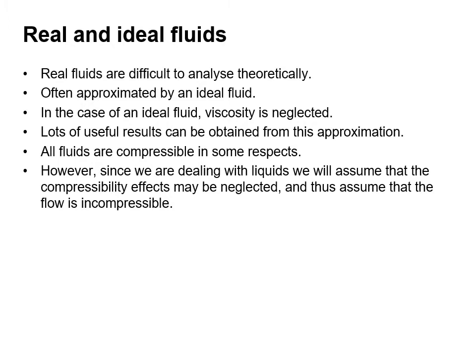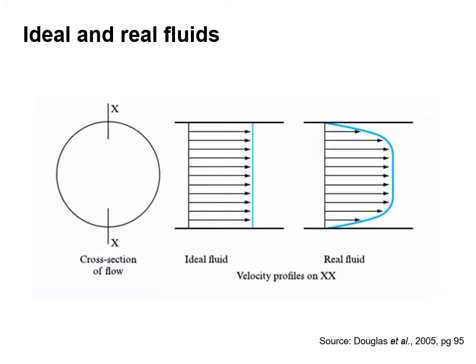flow is incompressible. In general, all fluid flow occurs in three dimensions, so that velocity, pressure, and other factors vary with reference to three orthogonal axes. In some problems, the major changes occur in two directions, or even only in one direction. Changes along the other axis, or axes, in such cases can be ignored without introducing major errors, and this then simplifies the analysis. Flow is described as one-dimensional if parameters such as velocity, pressure, and elevation, describing the flow at a given instant, vary only along the direction of flow and not across the cross-section at any point.